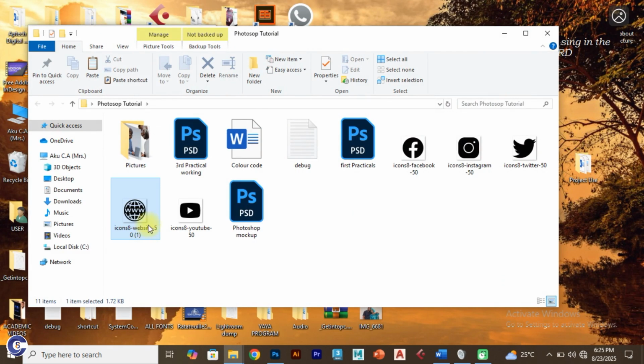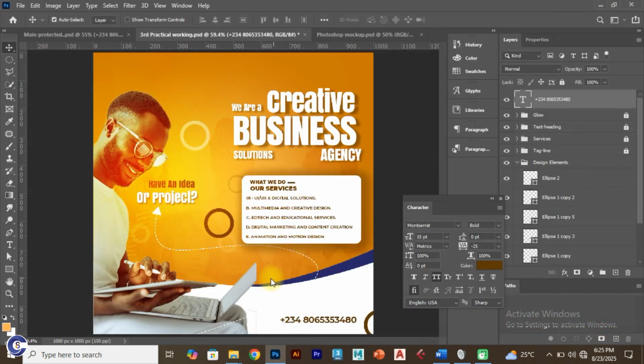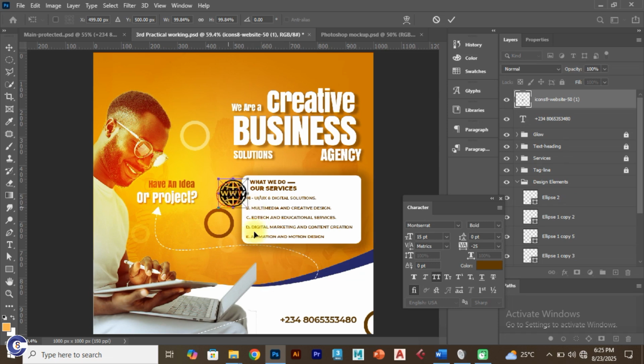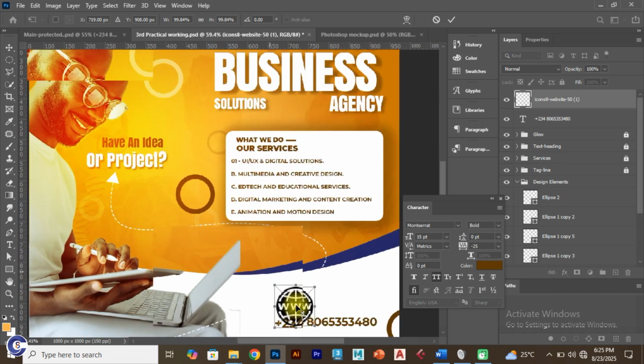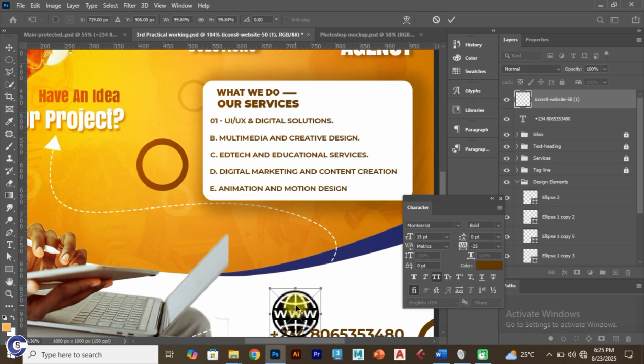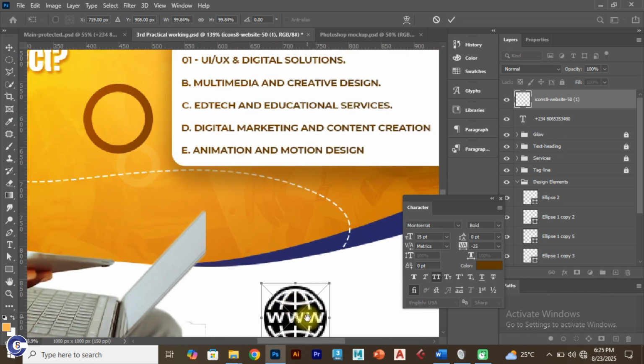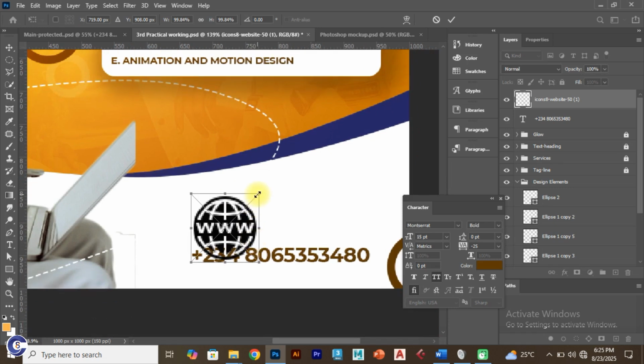Okay, it's here already, so let's drag this in. All right, we'll bring this into perspective. I'll hold my Alt and scroll my middle mouse button for zoom. Hold my space bar with my left mouse button to pan. Hold my Shift and Alt and drag inside like so. Bring this here. Depends on what I want.